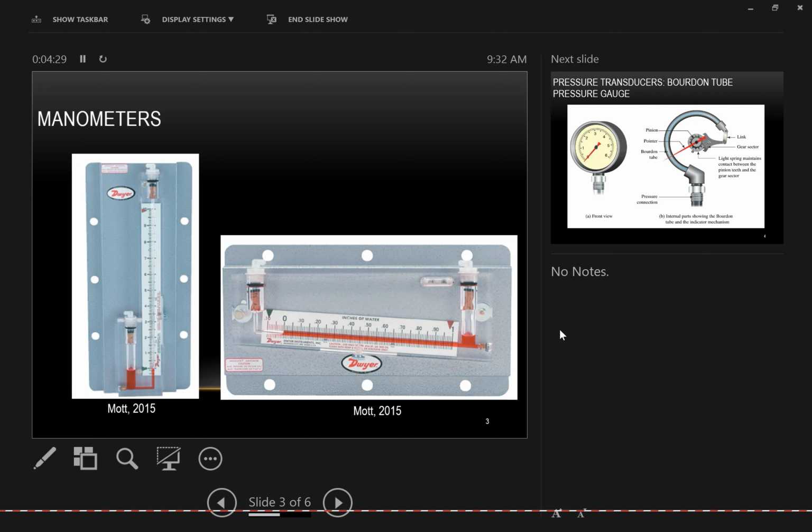Here we have a vertical one where this and this are hooked to either like a pipe or two different places to measure pressure. And this is what they call an incline one. And there's a port here and another port here. Okay. So as this liquid level changes, we can then figure out, based on that liquid change, the change in pressure, and we can use that in other calculations. Okay. So we're not going to do much with an incline, but we are going to do a lot with vertical ones, okay, that change your height.